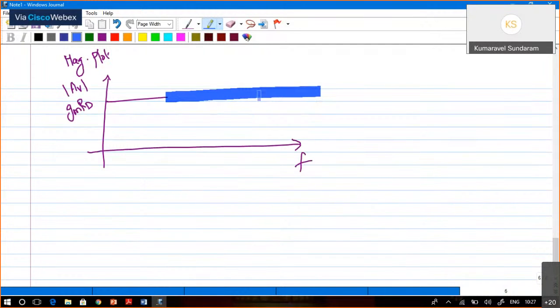It's a very basic thing only. Do you think the gain remains constant always as frequency increases? No. When the frequency is increased, after a certain point, the gain will start decreasing. Why? What is that point we used to call? So generally we call it the cutoff frequency. After a particular frequency, the gain starts rolling off, decreasing. Right? Why does it have to decrease?